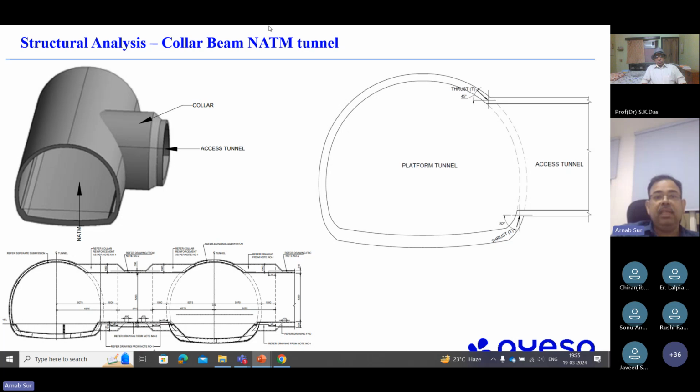For temporary lining, what we explained at the beginning of this presentation, since the access adit construction creates some additional ground forces on the tunnel, we already designed the primary support of this area, which portion is affected by the construction of this adit, for higher forces. So that lining is already capable of taking that.